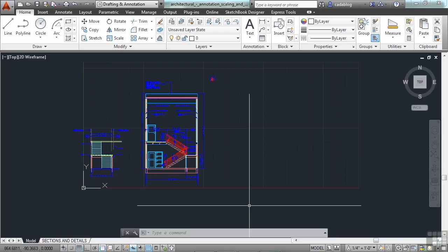Once you're done working in your file, you've submitted it, you've printed it, it's done, it's good, you're not going to work on it anymore, or at least odds are you're not going to, that's a good time to purge. Or if you're going to email a file to somebody, that's another good time to purge your file. Otherwise, I suggest waiting until you're done to purge the file, unless it's just way too big and you need the space. Because you never know when you're going to need that extra layer.